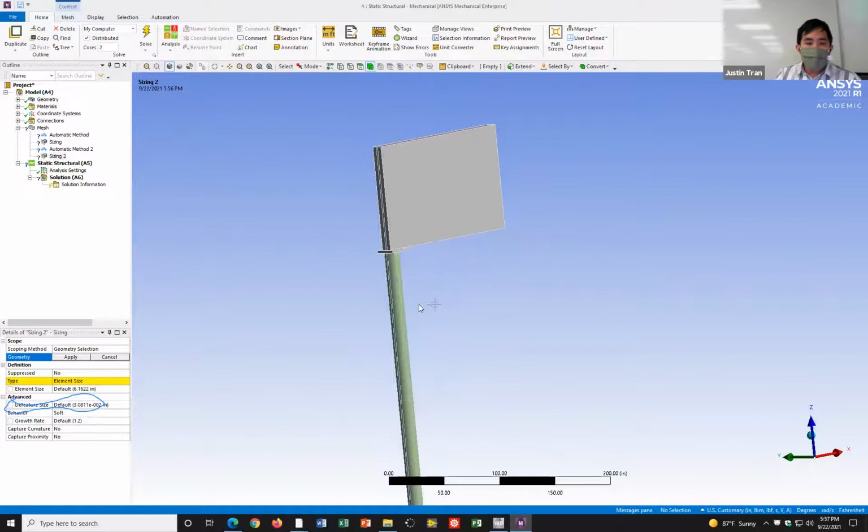And so for both the sign and the post, I want you to select things like the element shape, the element order, and the element size. Okay. And so when choosing your element size, I want you guys to think a lot about where you expect most of the stresses to be, and then pack most of your elements in that area. Okay. And in the regions where you expect there's not going to be that much stress, you can leave that one mostly alone. Okay.